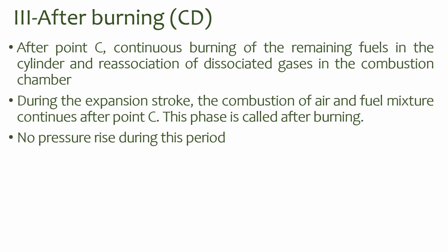The last stage is afterburning and it is represented by CD. After point C, a continuous burning of the remaining fuel in the cylinder and a reassociation of the dissociated gas in the combustion chamber occurs. During the expansion stroke, the combustion of the air and fuel mixture continues after point C. This phase is called afterburning, and during this stage, no pressure rise is happening.